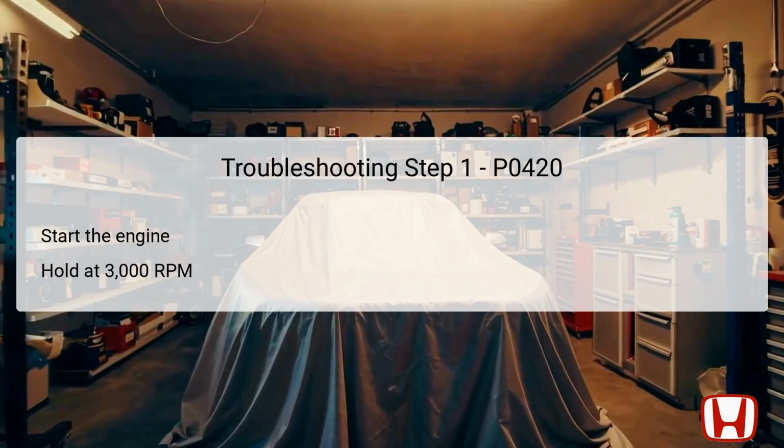This process should be continued until the radiator fan activates. This activation indicates that the engine coolant has reached its optimal operating temperature, essential for accurate testing. Once the fan engages, it's time to shift to the next step of the confirmation procedure, where the vehicle will further be evaluated under various driving conditions. It is crucial to observe the engine's performance during this stage.